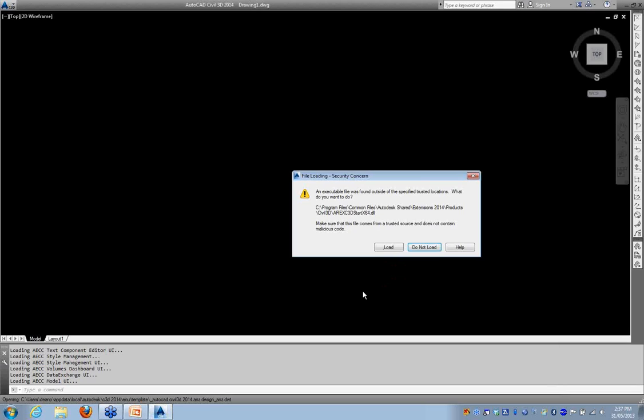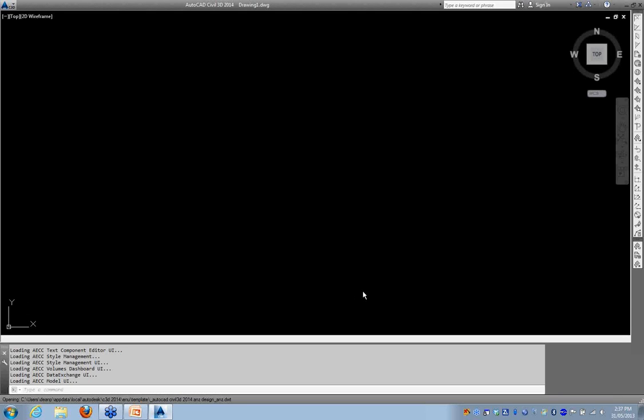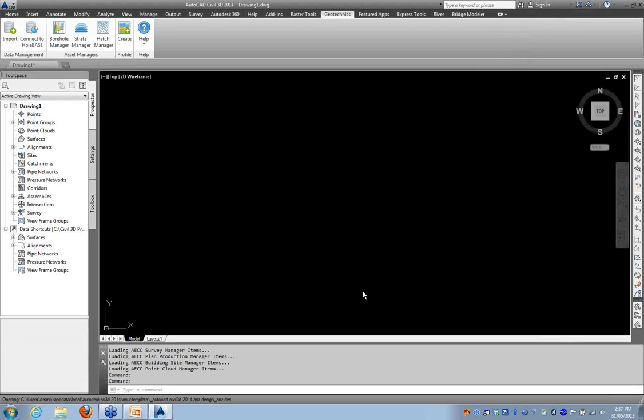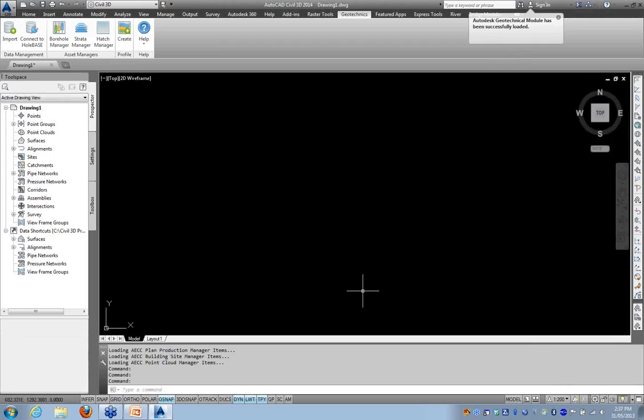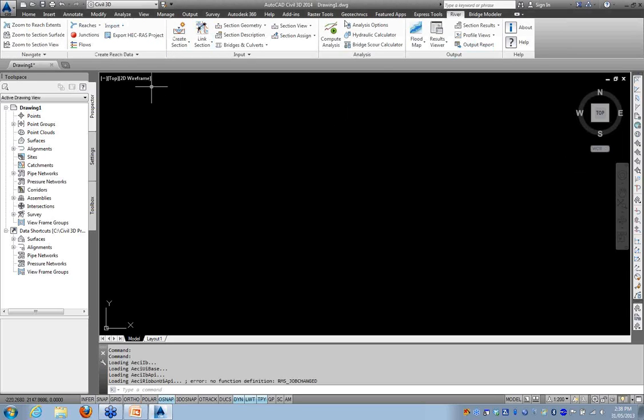It basically sets up the HEC-RAS model from a Civil3D surface, so you just cut your cross-section through a Civil3D surface and then can process that. You can also export to any of the HEC-RAS formats that you can then take into a full analysis. If you don't want just a steady state model, you can export it to the full HEC-RAS program. And this is it here up in the river tab, up in the ribbon, to do a flood mapping of a river using HEC-RAS.